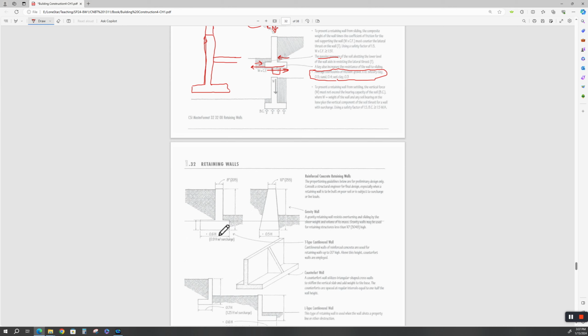It's naturally hydrating. And yes, I'm getting off into geek land. But now, when the coal-fired power plants came on, they had a ton of fly ash left over. So we started using fly ash to mix it with the cement for reinforced concrete. I was on a committee back in the 70s with the American Concrete Institute, and that was a big thing. We used fly ash mixed with the cement in the concrete, and we got the same strength concrete, same density concrete, and we were reusing.